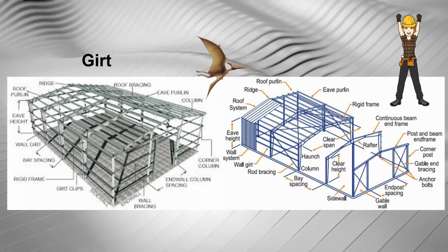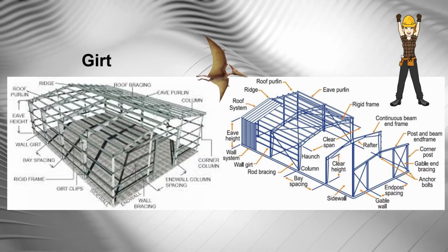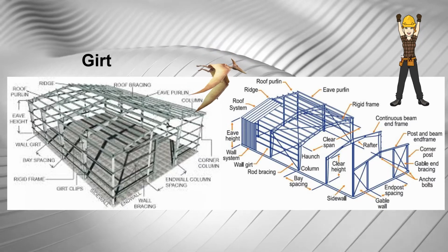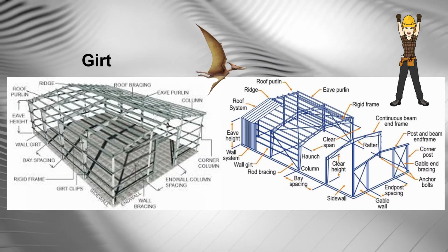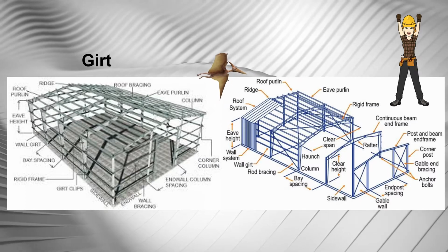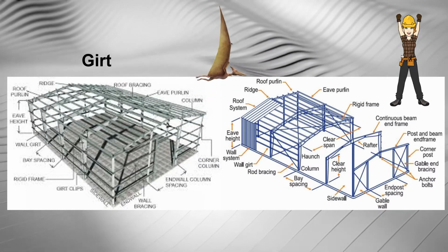Stabilizing rods are discrete brace members to prevent rotation of an unsupported flange of the girt. Sheet metal wall panels are usually considered to provide lateral bracing to the connected, typically exterior flange along the length of the girt.